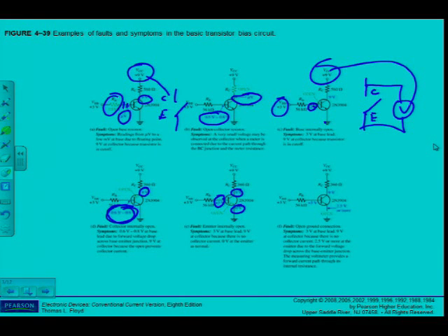So here in this case, you can see there's my 9 volts, so it means the transistor is in cutoff again. 3 volts there, but here at the base I should have measured 0 volts. I am not measuring 0 volts. So it seems that there's a volt drop between the base and the emitter, but it's not connected to ground. So I should have measured 0 at the emitter. So that is some of the faults that may occur.